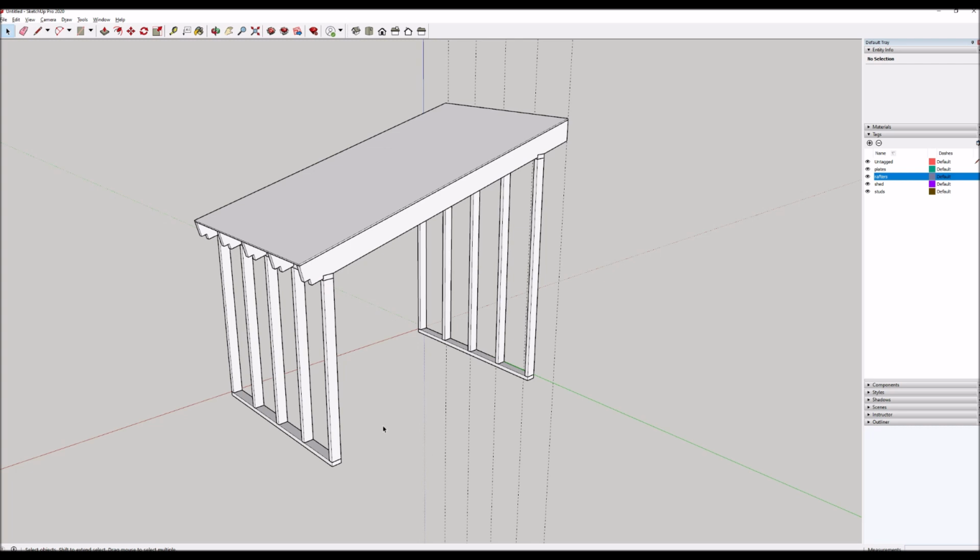Components. Make an object, put it together as a component, make a copy of the component. Now, if you change either one, either the original or the copy, both will change. So that's the difference between groups and components. And then we looked at the axes, the model axis, and if you make the object and then rotate it, you get a different result than if you make the object in the final sloped geometry.